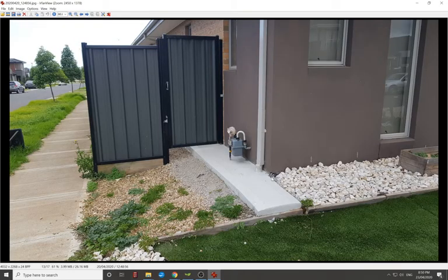I mean, look at this piece here. This just juts out. I don't know what their plan was there. Maybe they're going to join up a path there. It's odd. And I mean, the side's not dressed. This is what I was saying about the height difference before. You've got to do some landscaping there, but that's quite a severe angle. So you really should trail and finish off the side of this concrete here to make it presentable.